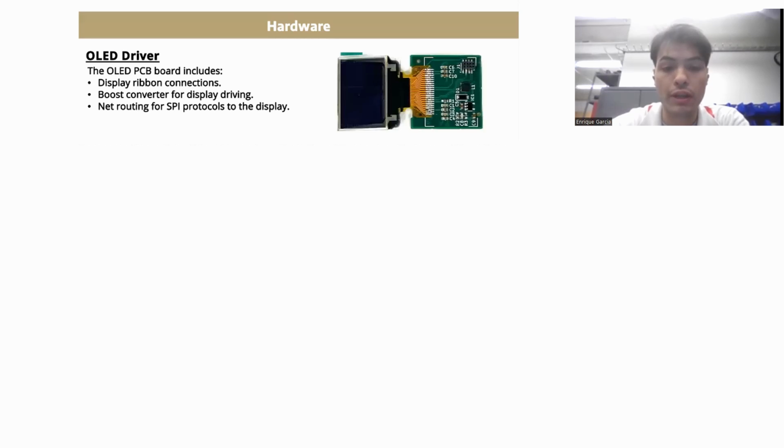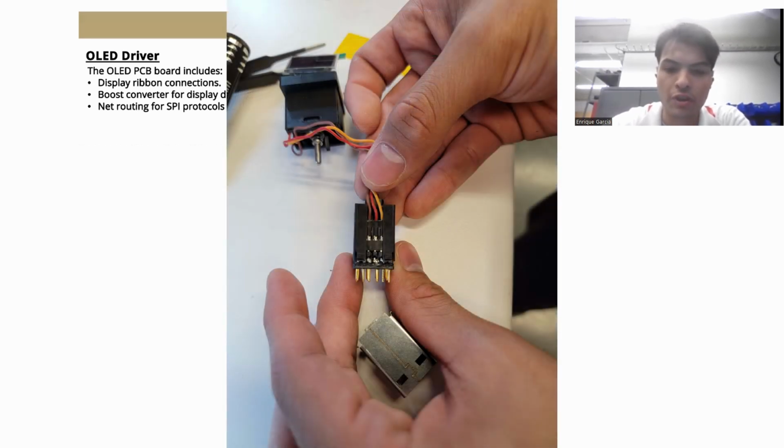The power delivery into the switch itself makes use of 3 pins connected to the interior, one being ground, one being the 3.3 volt, and the last one being a GPIO port. The switch's internal logic is able to supply either 3.3 volts or ground to the GPIO, and there is hookup wire soldered to the connectors between the various PCB boards that allows the power, ground, and the GPIO to all be connected together internally.